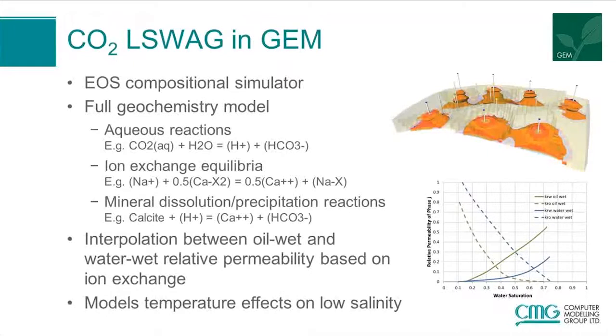In order to capture the wettability change, we have the option to interpolate the relative permeability curves based on the ion exchange. In the case that the injected fluid has a different temperature than the reservoir fluid, in GEM you can also capture the effect of temperature on the low salinity water injection.